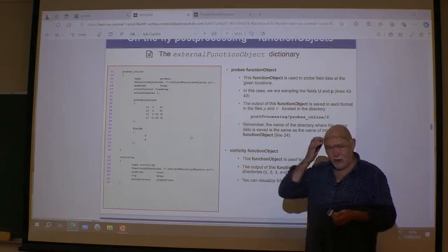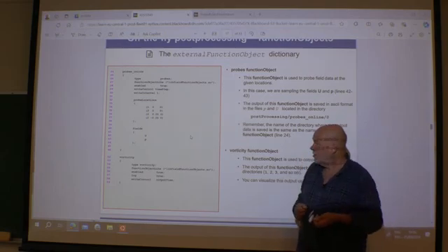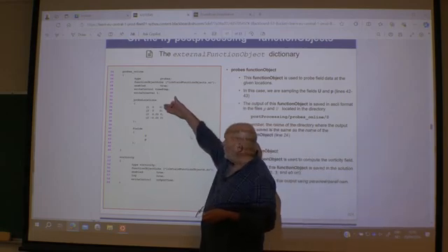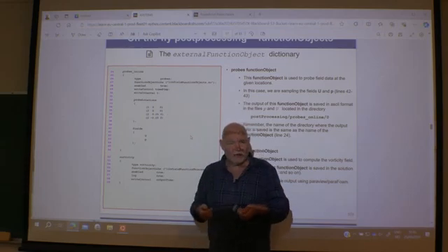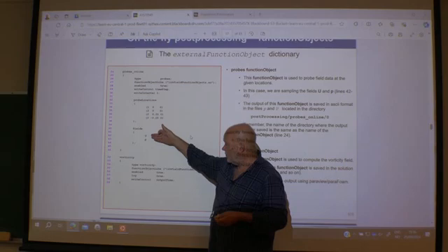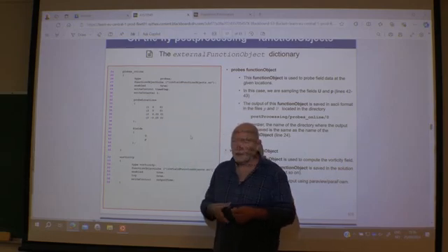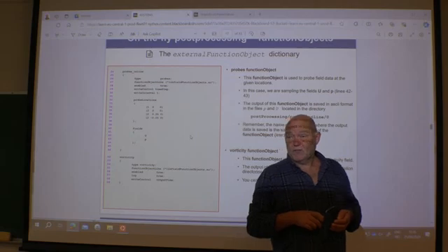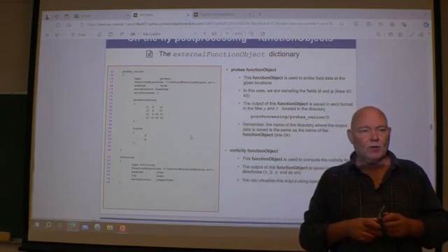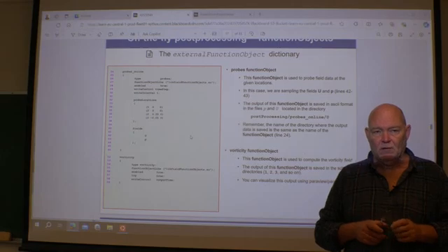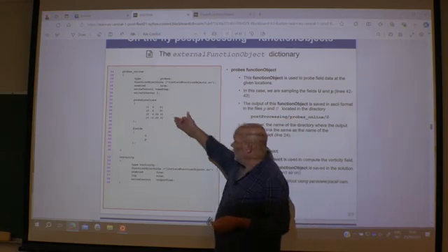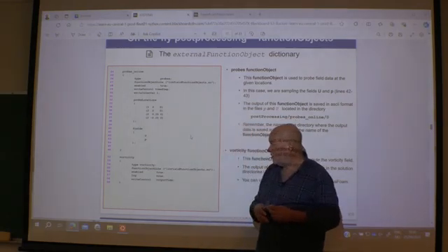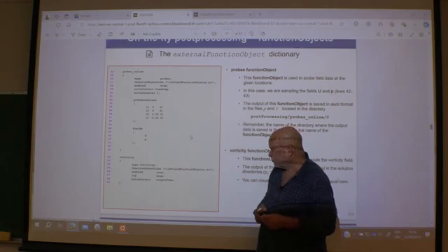But sometimes we have to try several times here. But okay, then you can put in several locations here, and then automatically you will have all these values listed for velocity and pressure at those locations. That can be very, very convenient, especially when you operate with different meshes. Then he will interpolate it for you for these locations. So that could be very, very nice indeed.